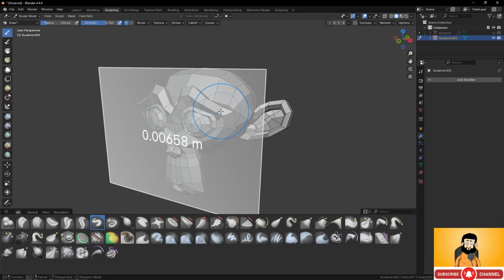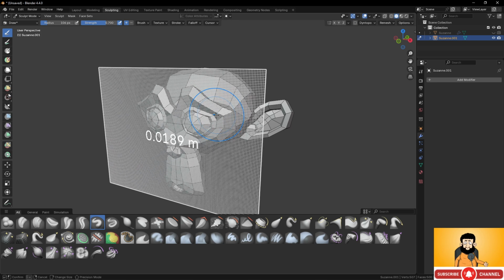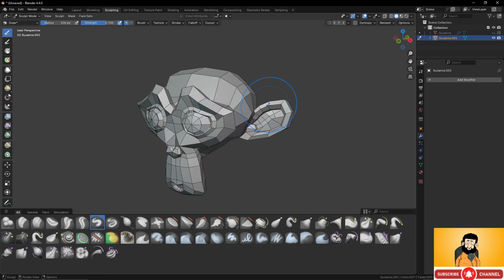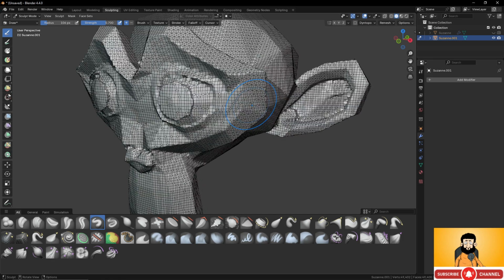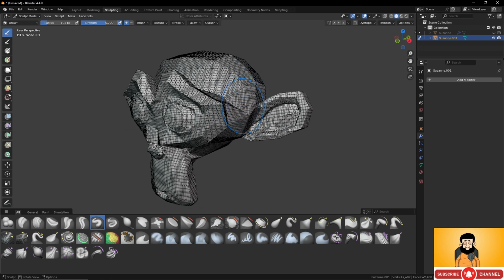For example, in the beginning of the sculpt, if you want to just create shapes, you will just use something like that, and Control R will apply the size that you wanted. So R to change the size, Control R to apply the remeshing.